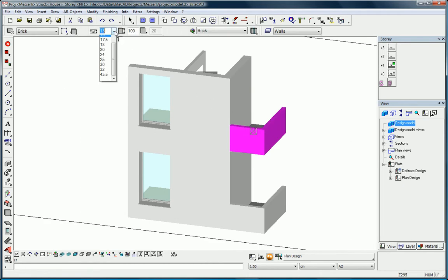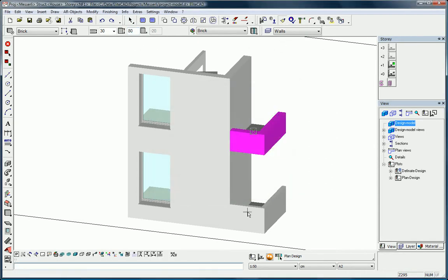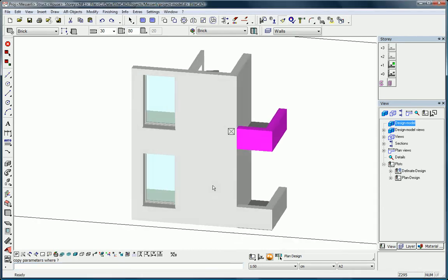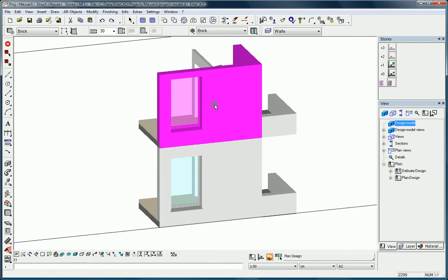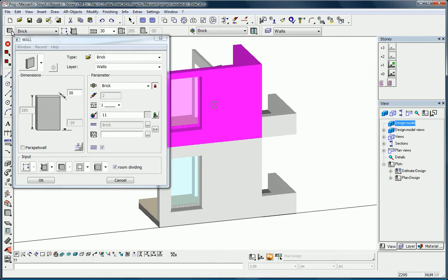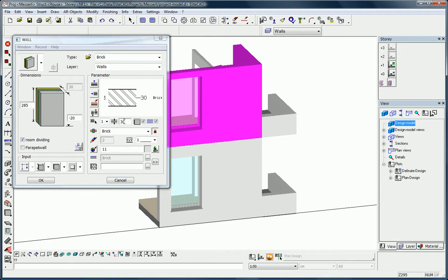All the components that make up the model, including walls, doors, windows, ceilings, roofs, etc., are parametrical entities, the geometry and sizes of which can be adjusted at any time. Here we can, for example, click on a wall. This wall is currently monolithic, and we want to convert it into a multi-layered one.